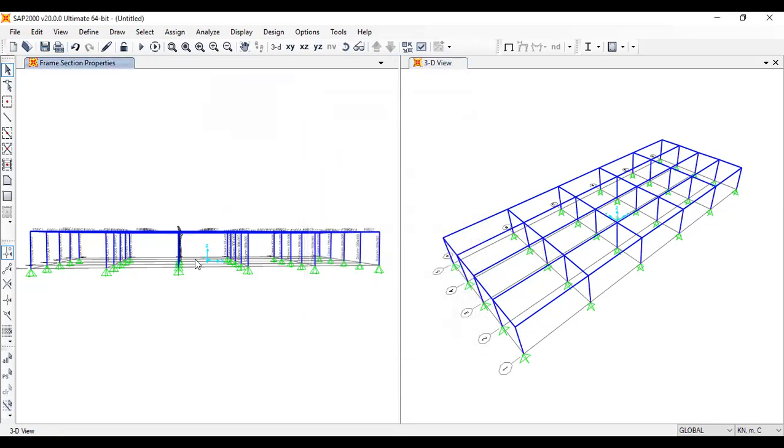That's column, right? And now all the things are deselected, so again for beams, I can select this top floor from left to right, because the whole thing is getting selected. Can you see? All the beams got selected. If I select it the other way around, columns will also be selected like this. Can you see? So you can't assign. So clear it and left to right.